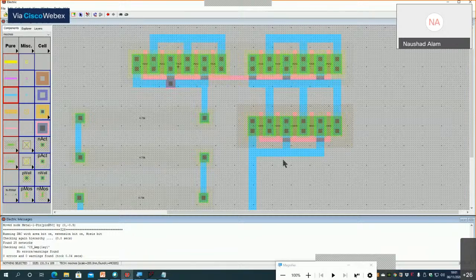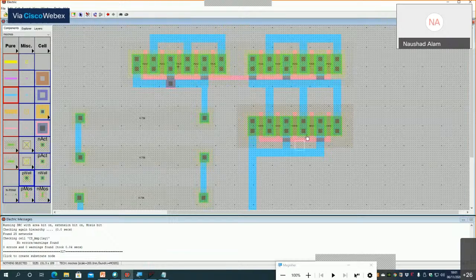So we know that the source of the N MOSFET and the well will be grounded. So now I go and select P well, because this NMOS is housed in P well. So I put a P well here, and then I'll edit the size of this P well.